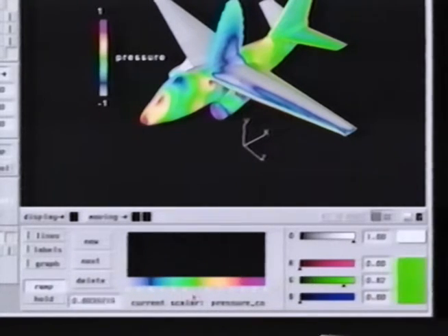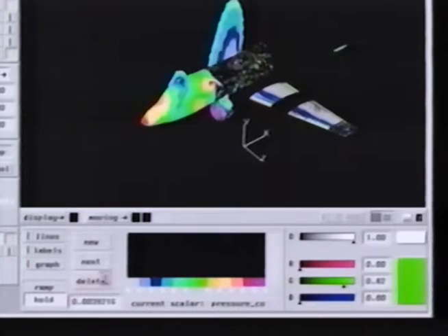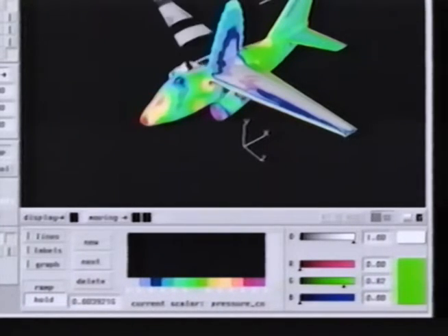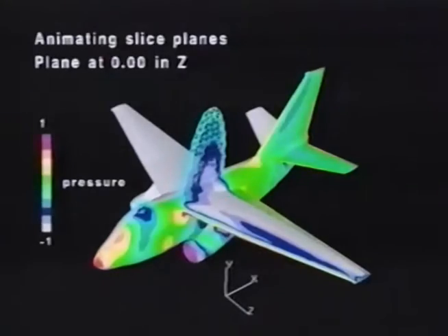The tick marks below the color bar are editable. Their positions can be changed interactively, as can their color properties. Tick marks can be easily added or deleted. It is the color map tick marks that create color interpolation boundaries for the default or ramped representation of data distribution. Their position determines where contour lines are calculated and displayed. In what the user interface calls hold color map mode, they are also responsible for positioning the banding intervals seen in this data representation.